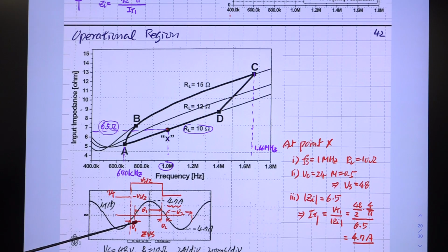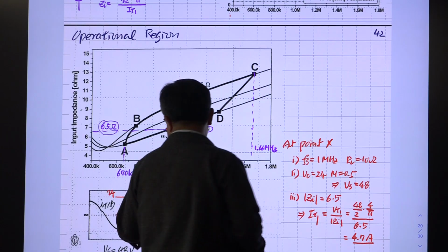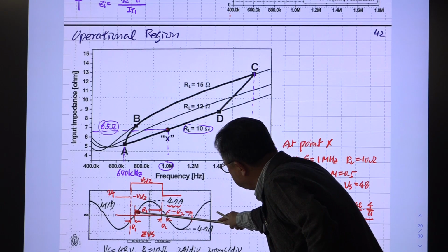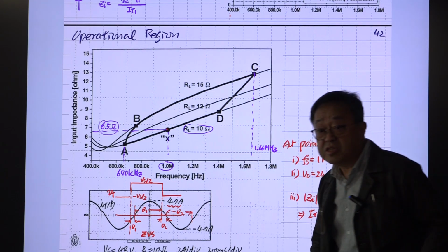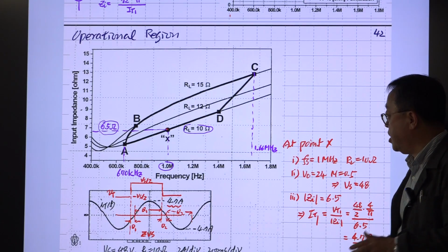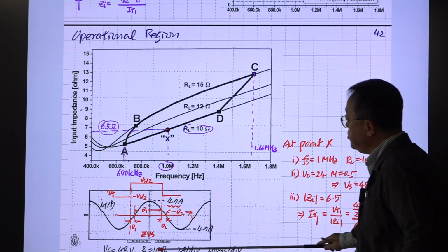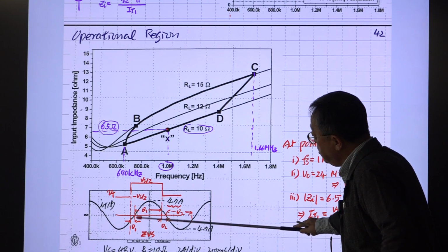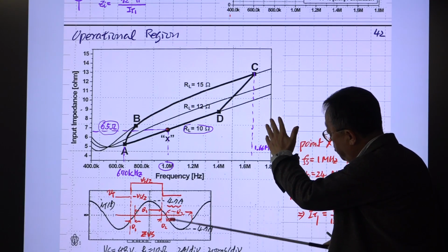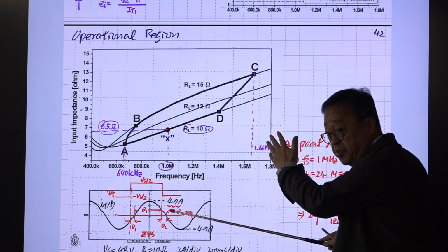That means during this period of time, D1, the body diode of the upper switch, is conducting. And later on, this channel is created, but after some time, the channel is delivering this current with a 0 voltage condition because the body diode is already conducting. So this confirms the ZVS operation for the upper switch and the ZVS operation of the lower switch. So this might be good.